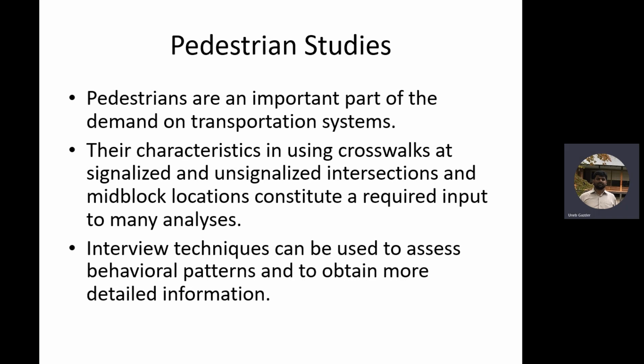Pedestrians, as I mentioned earlier, they are part of the traffic demand because of the new purview, right? We have to include all modes of transportation. So they are also part of the traffic demand, and basically we have to take care about their crossings. Sometimes we do pedestrian demand studies to know how many pedestrians are crossing, and from which place they are crossing. Then there is another important parameter, which is their walking speed. Even to know their walking speed, we need some studies. We may include interview studies for pedestrians as well.